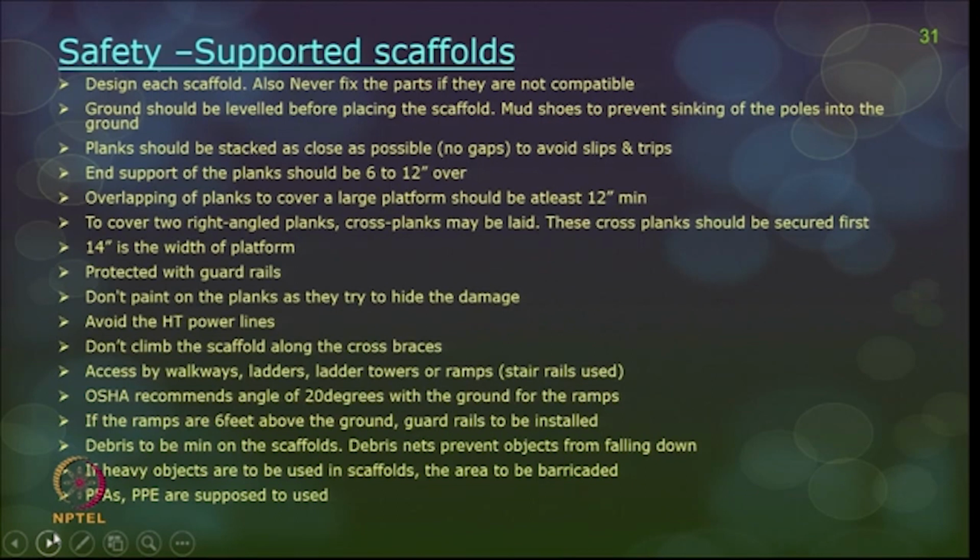And 14 inches is generally the width of the platform, and all platforms should be protected with guardrails, okay. If the height of the scaffold is 6 feet and above, you should have proper guardrail protection. And do not paint the planks.